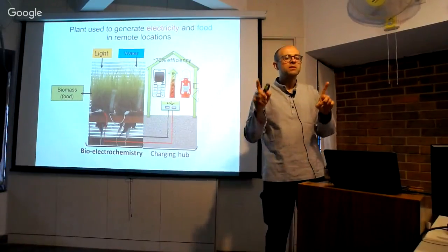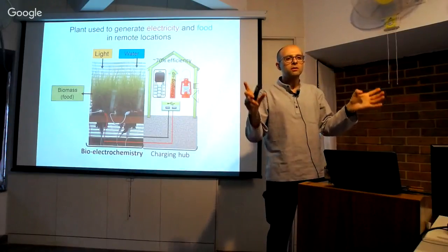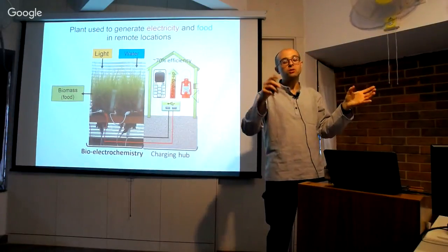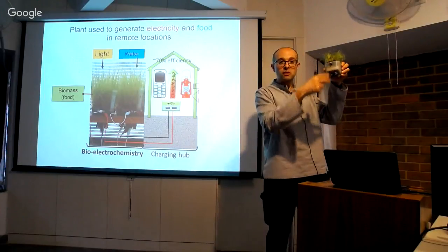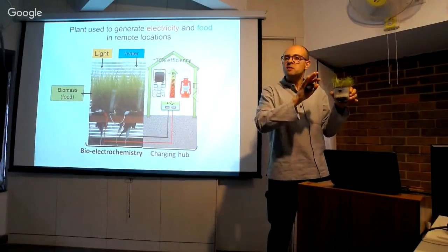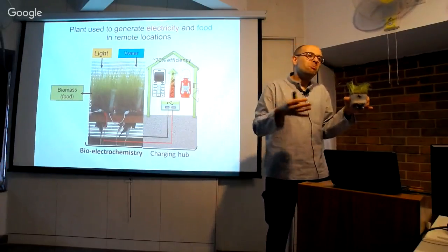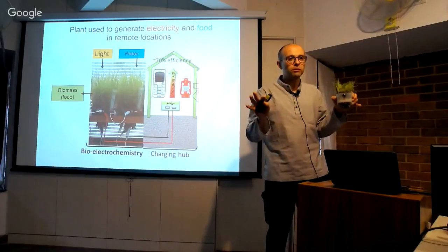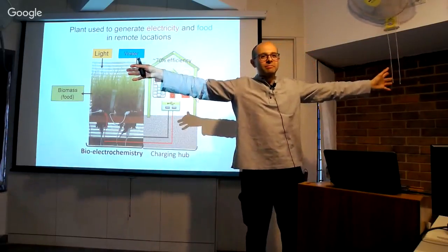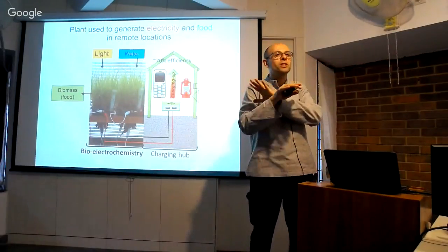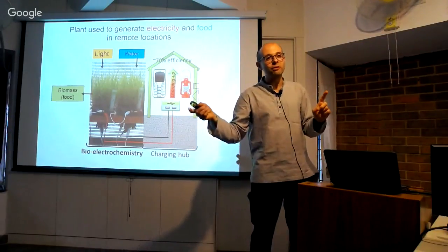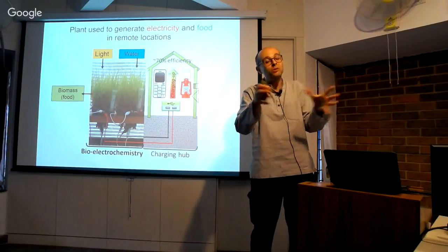The theoretical limit is dictated by the anodic and the cathodic reaction. So the redox potential of the reaction occurring at the anode minus the redox potential of the reaction occurring at the cathode gives you how many millivolts you can have from anode to cathode. I said theoretically it's up to 1.1. Practically, I haven't seen anything bigger than 800 millivolts. To be honest, generally I expect something around 500 millivolts. So this is one limitation that you need to take into account. So if you create a huge one, you get potentially a lot of current, but the potential is going to be 500 millivolts. Therefore, you need to consider how many volts you want to have, do a calculation, and create smaller ones in order to collect in series.